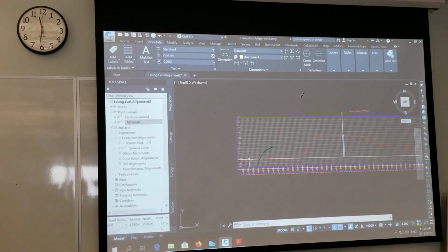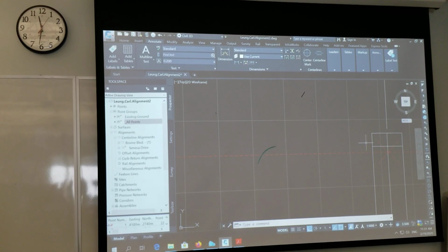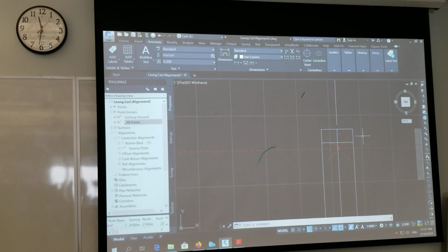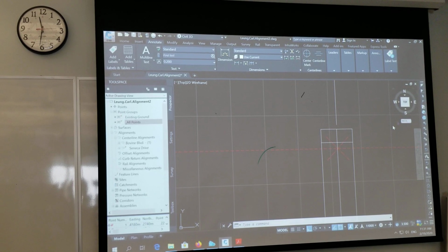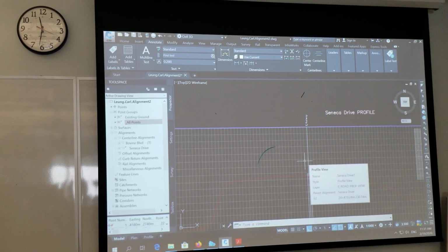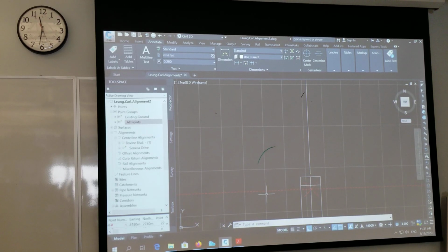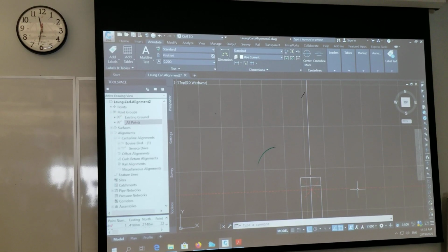So when I draw my profile here, my new profile of the new road, I want that profile to be inside of this rectangle over here, because I'm keeping the criteria of only having 0.2 meters difference from the minimum. Because this is the minimum. In theory, my road could go here, but I don't want to make it too expensive, so I created a maximum that sets 0.2 meters away from the minimum, which is this rectangle over here. So when I'm drawing my profile, my line has to go through this line over here. Does that make sense? Yeah?